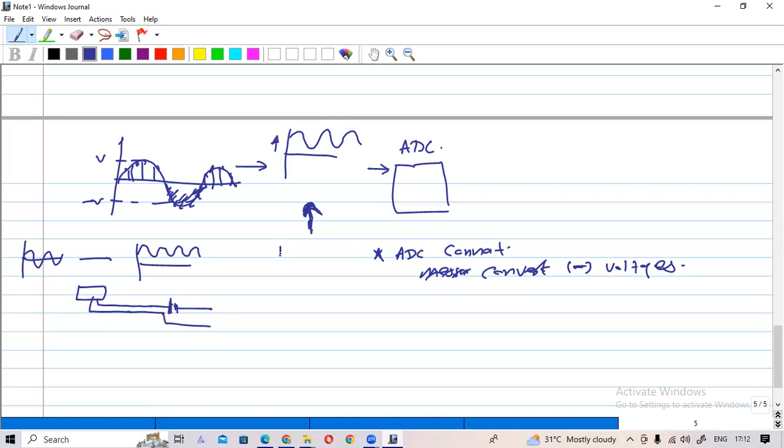We call this DC offset. Actually, for a signal generator, you do not need to add a battery or something. There is a feature called DC offset. But here, for this signal, maybe you have to add another DC voltage. You have to add another DC component. That is DC offset. Then this signal is shifted. So these are basic things. You should know that.